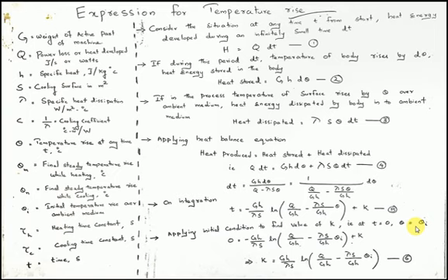It's not 0. The initial temperature rise will have a value of 0 only if the machine is starting in cold condition. What is cold condition is already said now. So you must understand the difference between the cold start and the machine starting after some frequent operations. Hopefully you have understood the difference. Let's get back to the derivation.